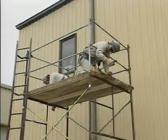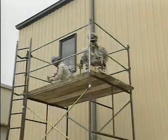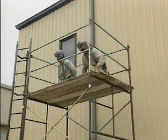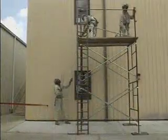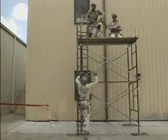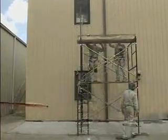The disassembly of a tubular welded frame scaffold is basically the reverse of the assembly. After the green tag is removed to indicate that the scaffold is unsafe for workers, the toe boards are removed from around the scaffold flooring. Then the upper and middle guardrails are removed, along with the guardrail posts. The upper sections of the ladder are then disconnected, and the scaffold flooring is removed.